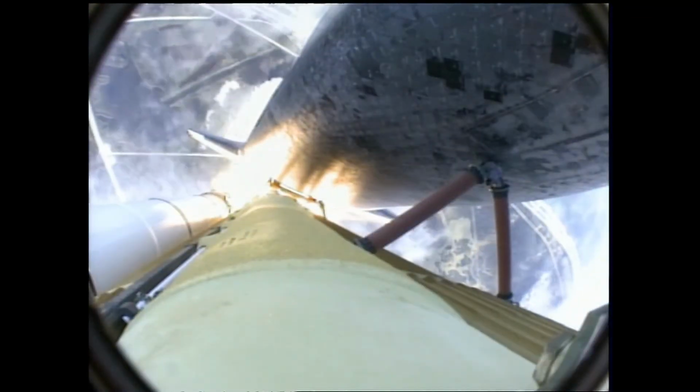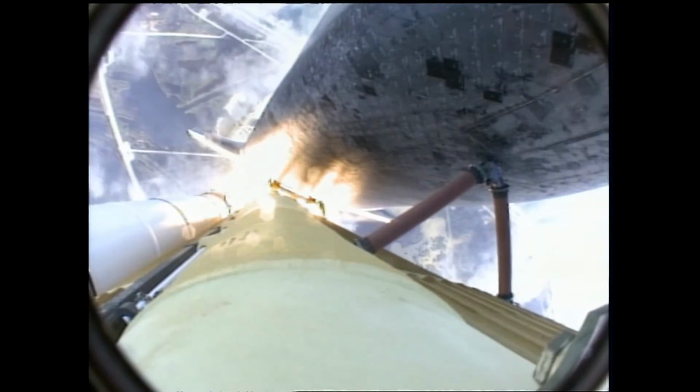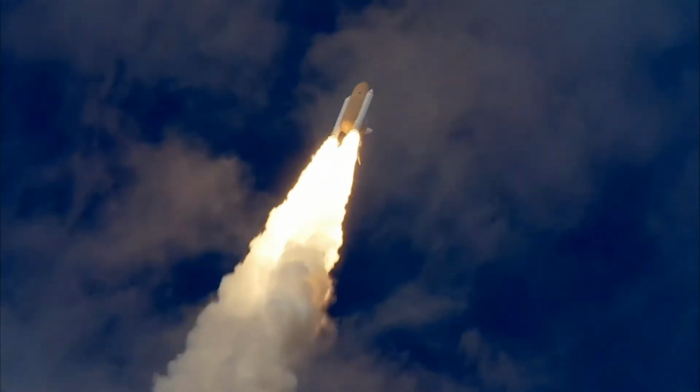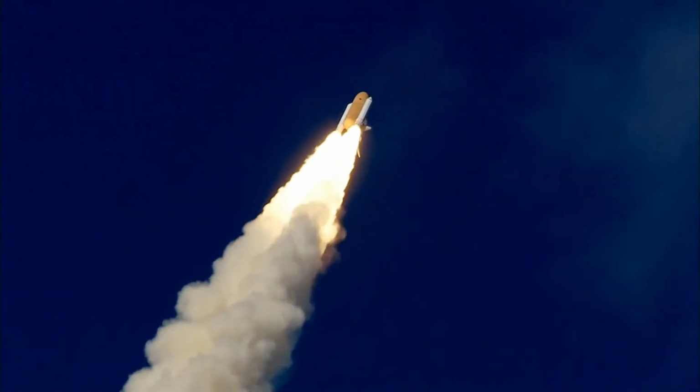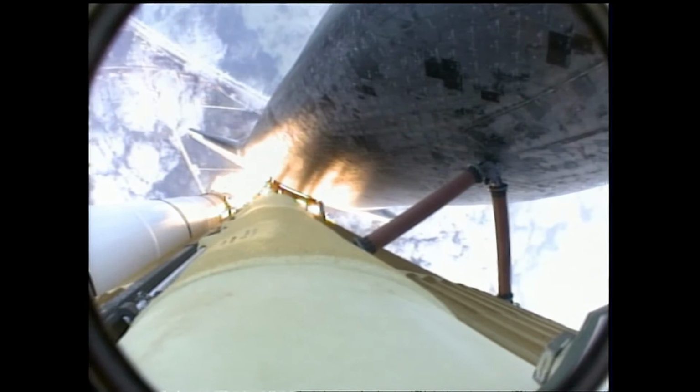When the exhaust pressure at the end of the nozzle gets below the pressure of the outside ambient air surrounding it, the ambient air starts to squeeze in on the exhaust gas. When that pressure gets even lower, the squeeze will cause the exhaust to peel off the nozzle walls and form random shockwaves and spikes that can tear apart the engine.